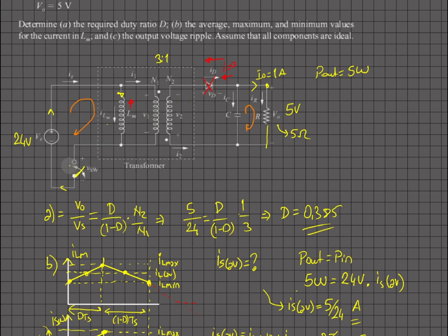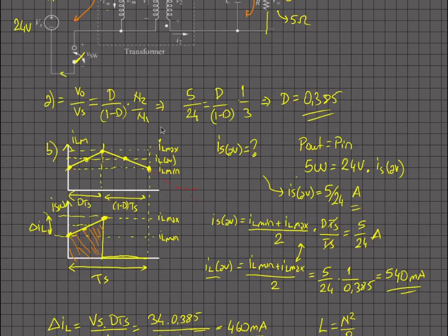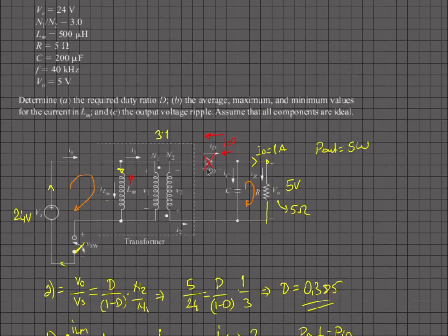Whenever I am turning on the switch, the diode is turning off, and while it is turning off you will have reverse recovery losses during that instant. So having the current at 0 before that transition occurs is also good for your diode losses.